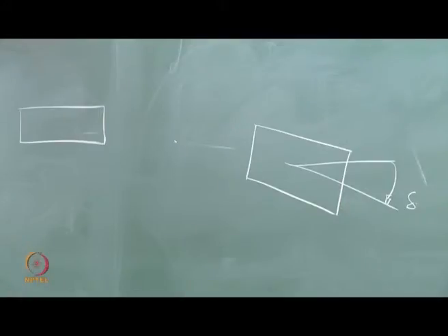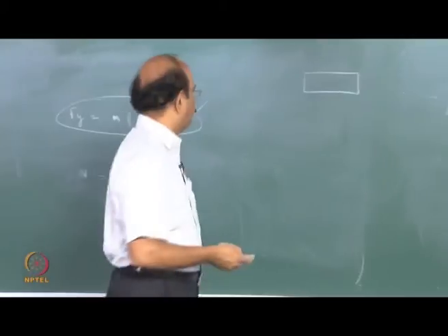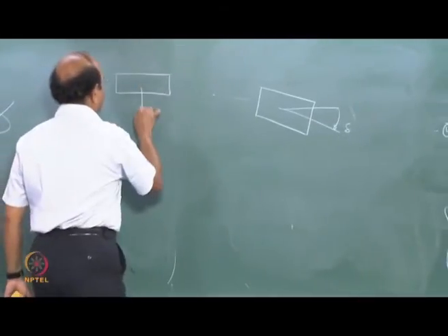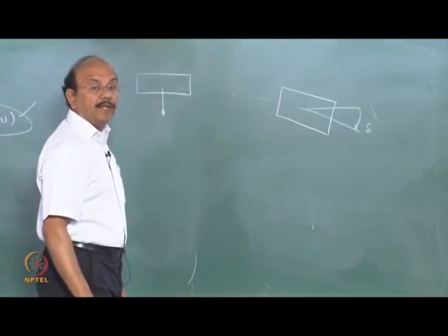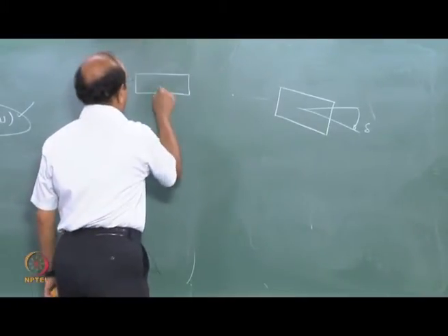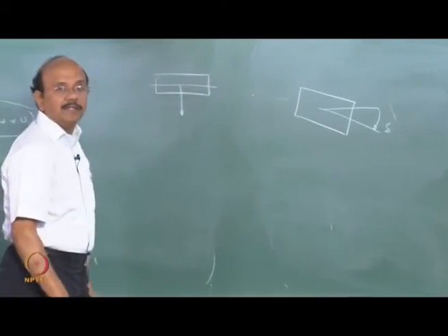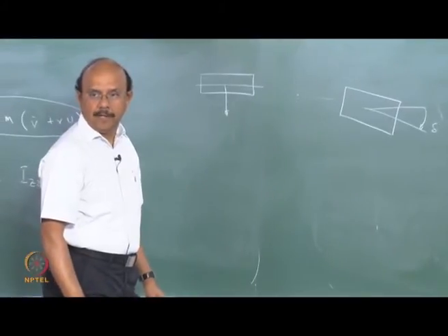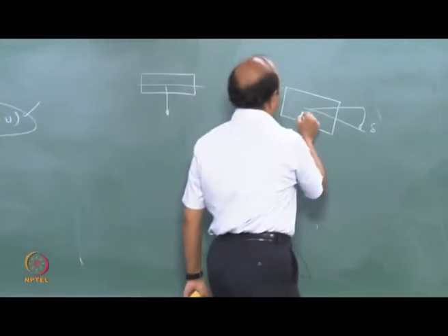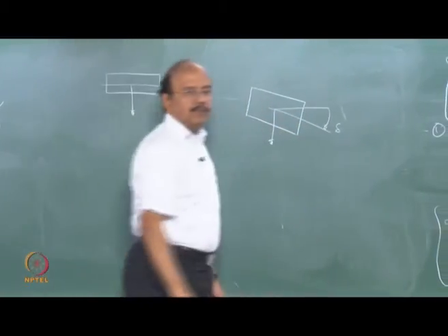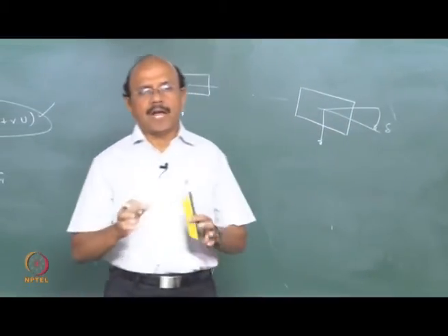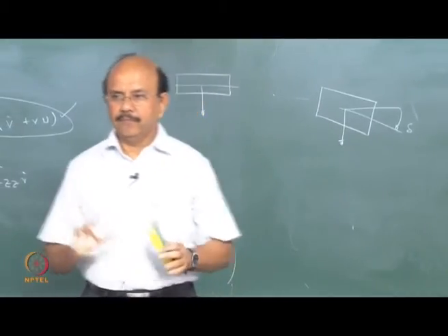Now, I'm taking a turn. When I take a turn, I will of course need this Fy which we have been talking about, right? And how is Fy created, or how is it generated? We have already seen that this is due to the slip angle. So if this is the force that's acting, there are small angle differences which I'm going to neglect, right?